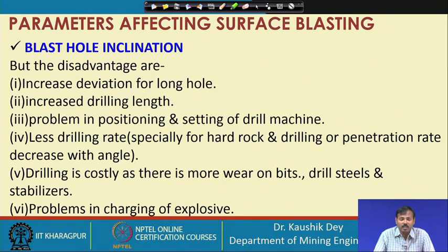But the disadvantages are that the deviation of the drilled holes is more, especially for long holes. The drilling lengths are also more, and the drilling cost may often be significant. In those cases this increased drilling length may alter the economics of the blasting. The drill machine positioning and the setting of the boom is very difficult, and an expert drill operator is required for that.